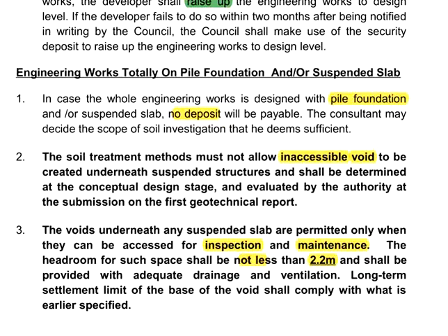Personally, I believe it is to prevent the accumulation of any natural gas that can be combustible or that may be toxic. There may also be concerns with the void underneath the suspended slab, which could be the habitat of wildlife or a breeding place for mosquitoes. These are other issues that can come along with the suspended slab system. However, as far as the structural stability considerations, as well as the functionality issues, suspended slab systems may be used.